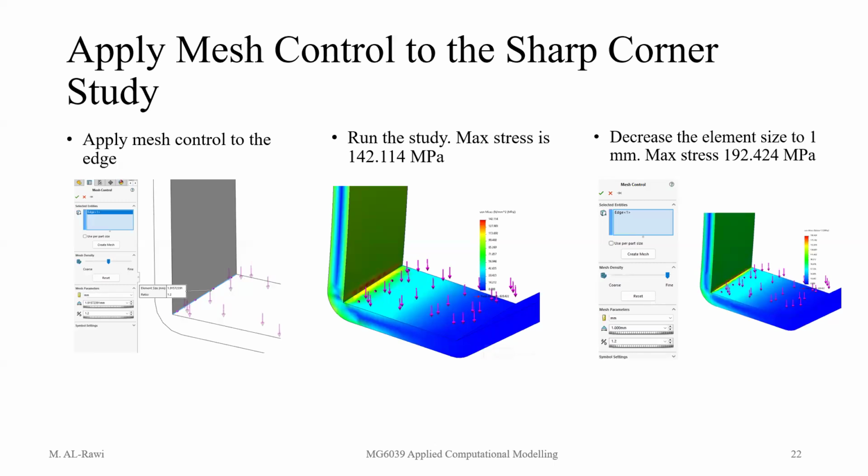And also, because Shivam, you've done fabrication. You don't leave this edge like that. It will break very quickly. So always you weld it, and the weld will give it this kind of a fillet of welding, right? Either that way or that way, depending on the use of the brackets. And that is to strengthen it, to give it enough strength as a structure with the material properties to make sure it will not be a weak area.